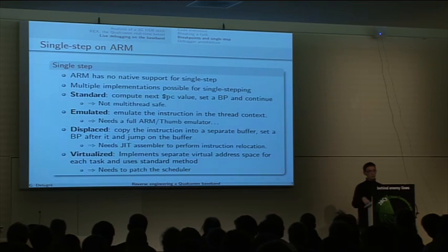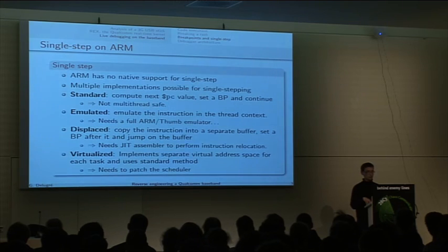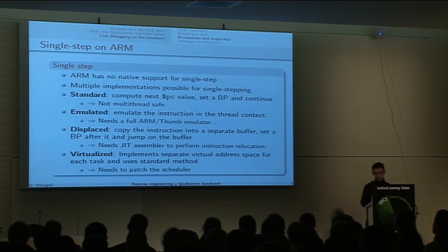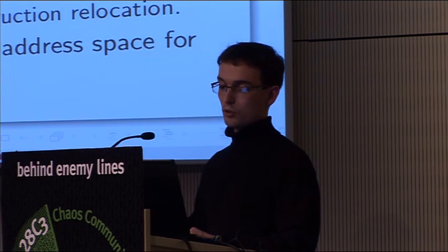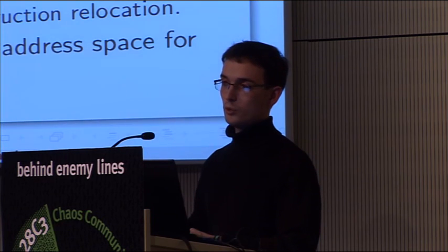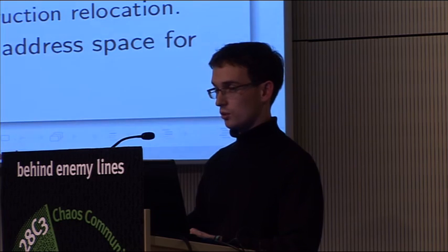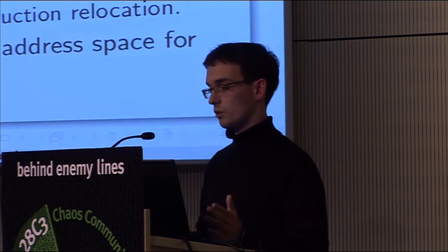The solution offered by GDB in a multi-thread context is to use displaced breakpoints. It will use a scratch buffer where it will copy the instruction. It will put a breakpoint after the instruction, set PC on the scratch buffer, and resume the execution. In this way, you do not put the breakpoint in memory where the code really resides, and so the other tasks can continue to execute without triggering exceptions.